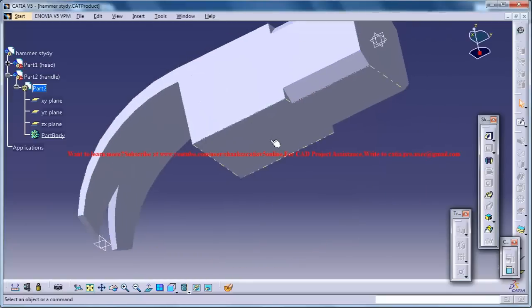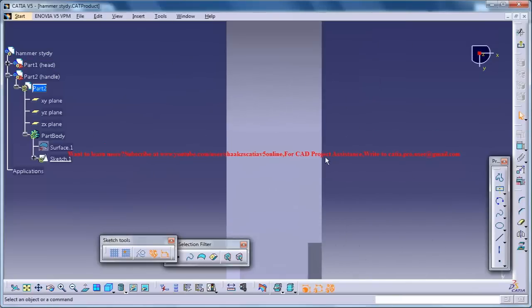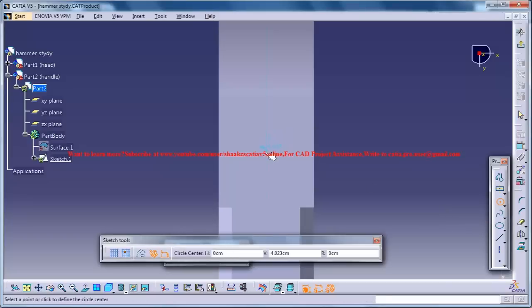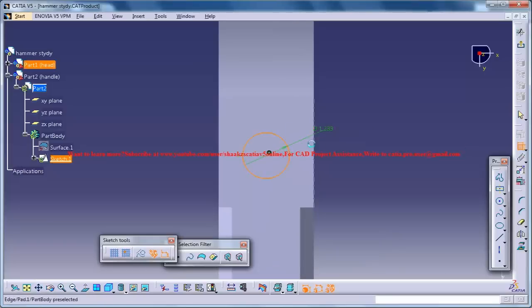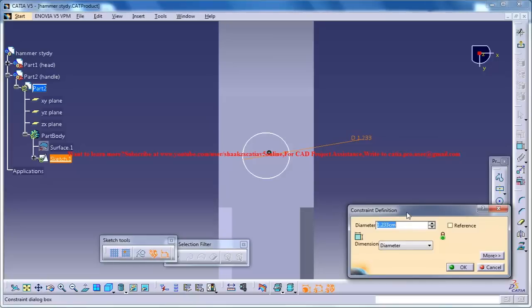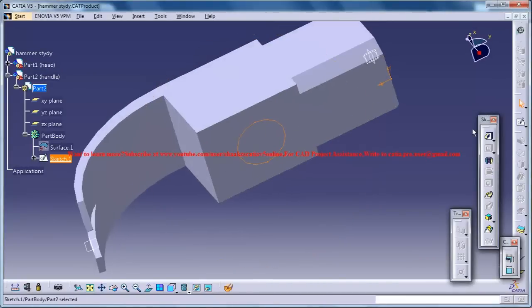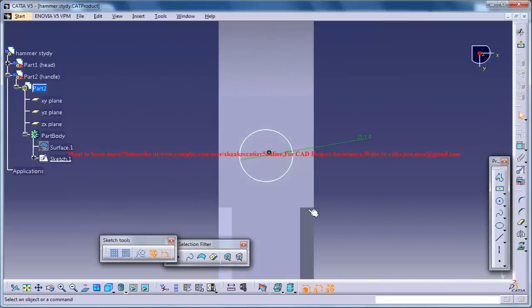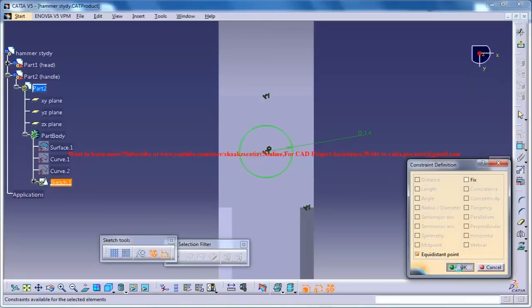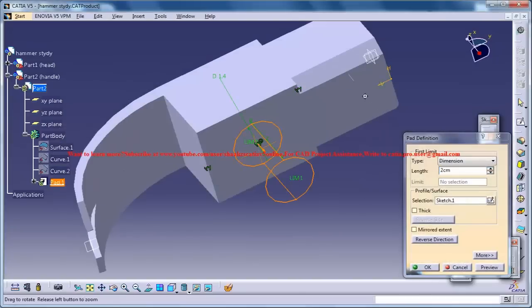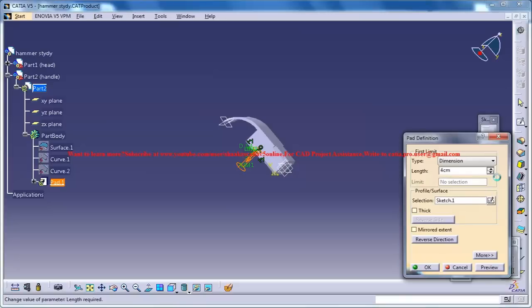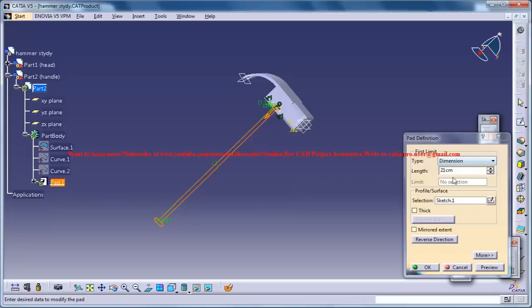Now what you can do is select this face and go for sketch, and just create a circle, simple circle, and just give a dimension of 1.4 maybe. That is something between these two. So for doing that, go to the sketch and go for that. Just increase it and just see how much is required in your case. Maybe 21 will do. Is also fine.